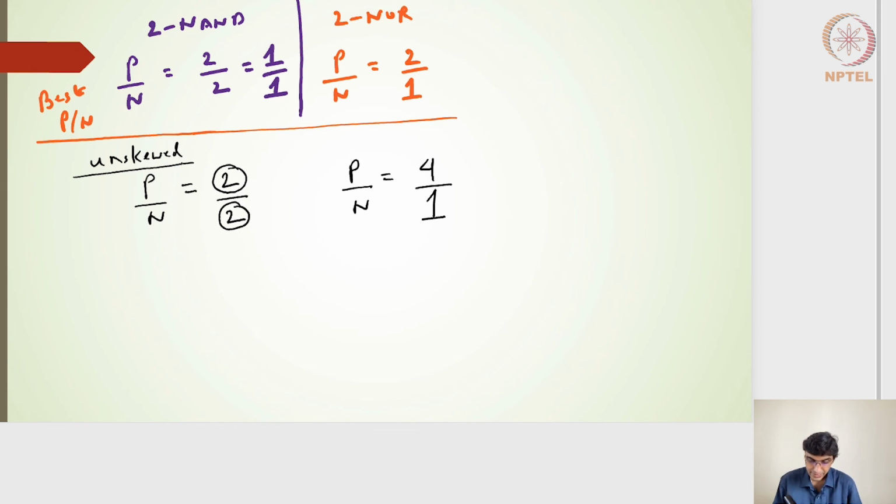here, if I have the size of 2 and 2, I will have the same falling resistance and then rising resistance. So I'm going to write it as the rising resistance and then the falling resistance turns out to be R, right? And it matches with that of the 2:1 inverter.